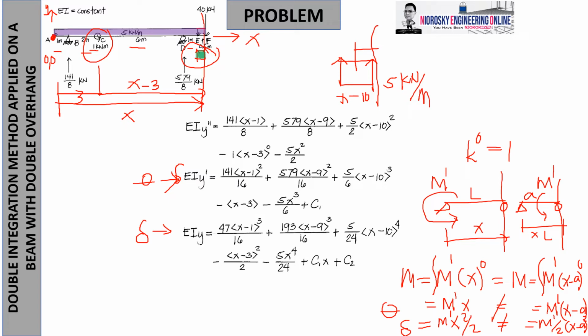So therefore, you notice that if x minus 3 raised to 0 is integrated, then 0 plus 1 is 1 over 1. And if you integrate again, it becomes squared over 2. So there's a difference. If you forget that, it will become only minus 1. Let's say you integrate this, minus 1. When you integrate this, it becomes minus x. When you integrate again, it becomes x squared. So that is wrong. The sense will change, because your load is located here, not at the far left end, which would make x alone the moment arm.